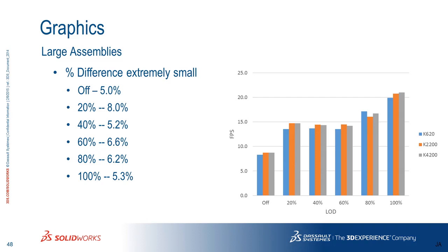And the reason for this is, Adrian, I think you have a little bit better explanation than I do. What ends up happening is when you get into large assemblies with SolidWorks, the number of components matters and the depth of the assembly matters. How many layers you have, that matters as well. Which really stinks to me because we tell our users to build in the depth you need, especially for a BOM or something like that. Yeah, for a bill of material. But also for managing your model, it's much easier. You don't want a flat model, right? But for graphics, it would have been better.